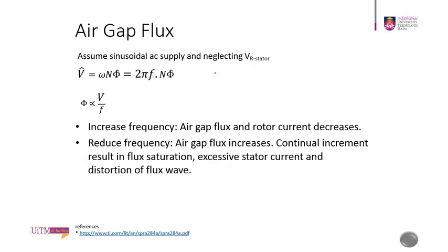Again, if we look at the equation, assuming a sinusoidal AC supply and neglecting the stator resistance voltage drop, you can see there is a significant relationship between your voltage and the frequency.